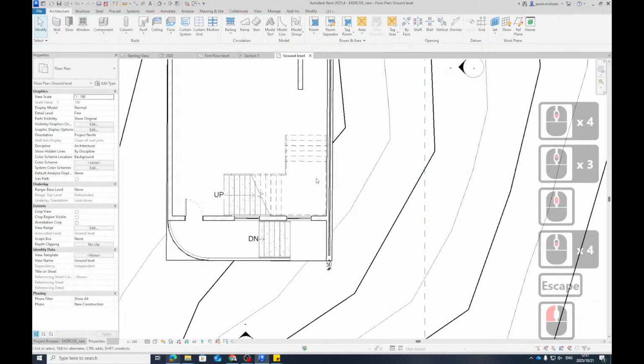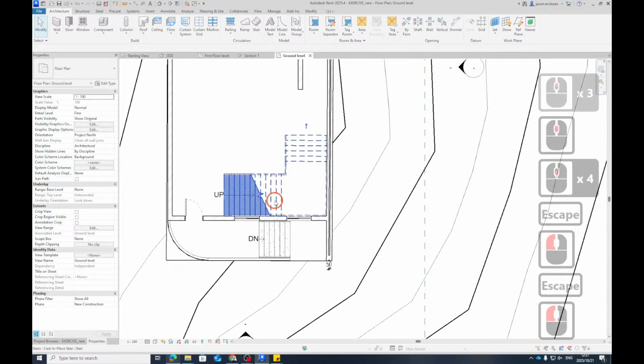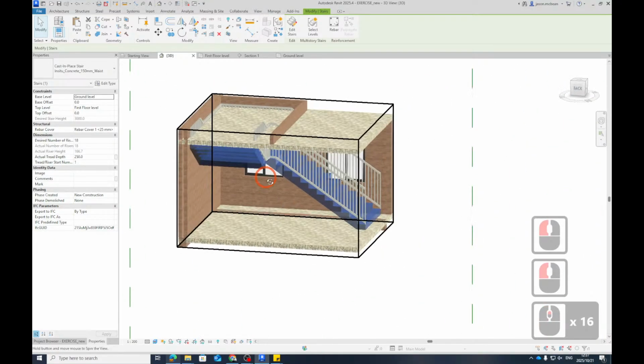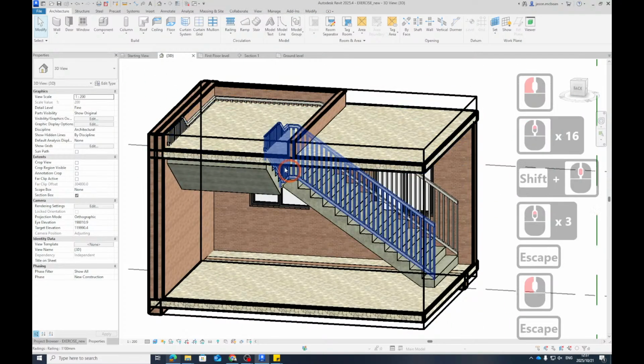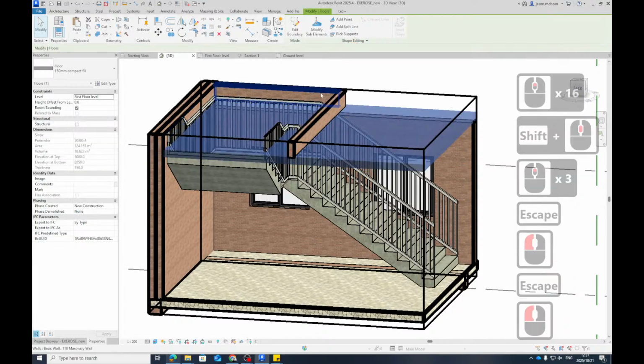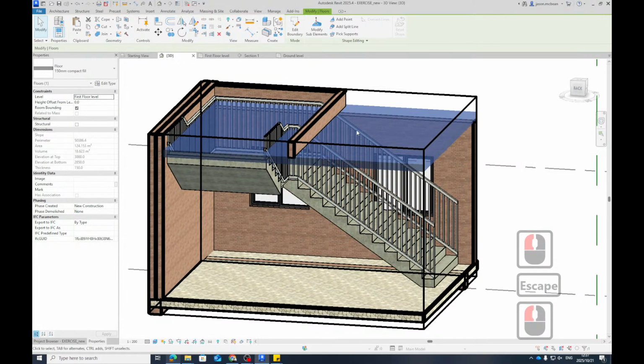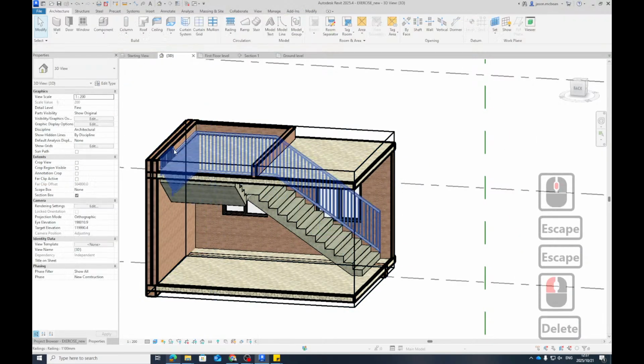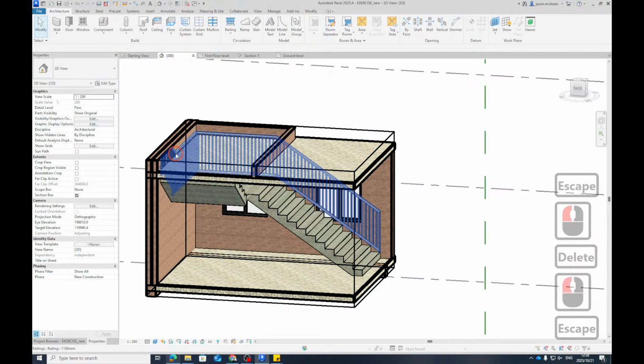So if I go to finish now, guess what? I love it. Now you cut out the opening here, this is how quick, it's very quick. But you've got a wall here, so your stair might not work. You've got a headroom issue there. Oh yeah. You might have to pull this back. Yeah, but these are going to be so long, it should be fine. Let's see. But remember, you might have an issue. But this is what's cool about Revit. You just start the stairs somewhere else, totally up to you.